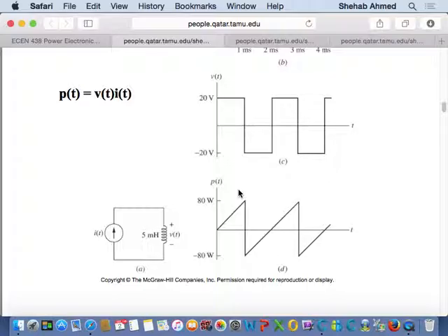So you charge a capacitor, and then you utilize that charge in a circuit. You charge an inductor. How do you charge an inductor? If you apply voltage, you build up a magnetic field. So the energy is stored in the magnetic field around the inductor. In a capacitor, you store the energy in the charge on the two plates that are separated by the dielectric.